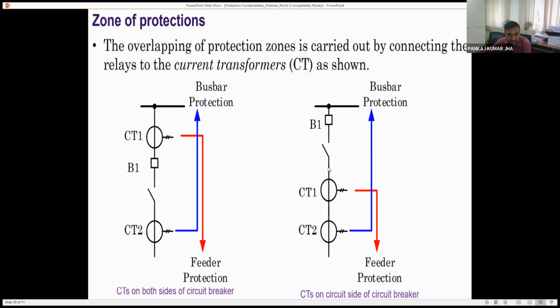So this fault is in the reverse direction. The feeder protection will see the fault, but it will see it in the reverse direction, which is time delayed protection, maybe 500 or 350 milliseconds, depending upon the practice of different utilities. So the feeder protection will see the fault in the reverse direction and it will not operate. So the fault will keep on persisting in the system. To isolate those types of faults, we need some other types of protection that we will discuss separately if time permits.